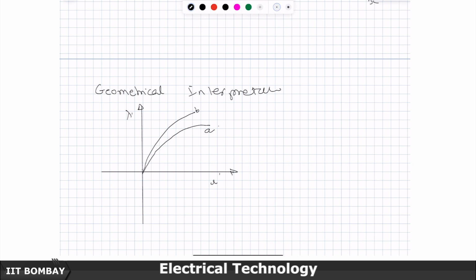Now, suppose I am somewhere here. So what happens here? Lambda remains constant. Our force equation was f_FLD equal to minus the partial derivative of W_FLD with respect to x. That automatically means lambda is constant here. So, I have to put a straight line like this.